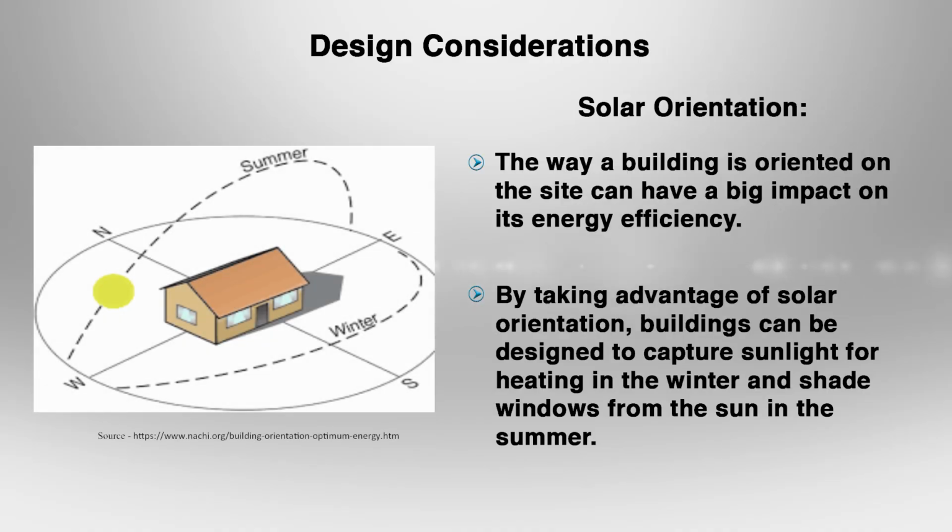In this presentation, we will explore the efficient building envelope, starting with understanding the local climate. A building designed for a hot desert climate would not perform well in a cold mountain region. Climate responsive design principles help us to create envelopes that are optimized for the specific environment. In hot and dry climates, maximizing shading, utilizing natural ventilation strategies and choosing light colored reflective materials for the envelope can significantly reduce cooling loads.